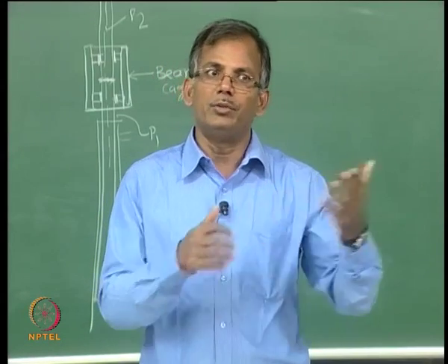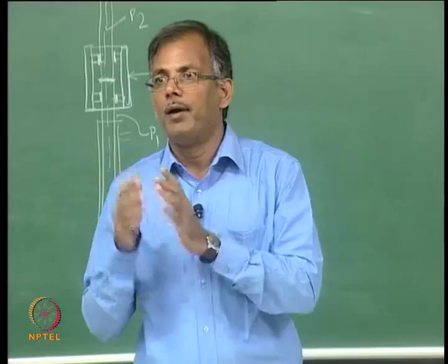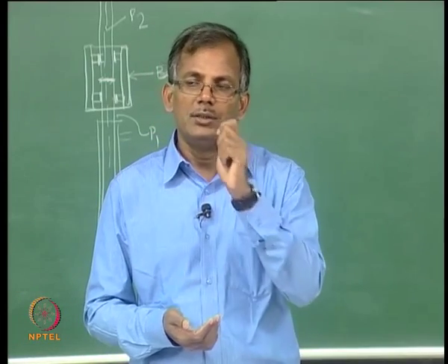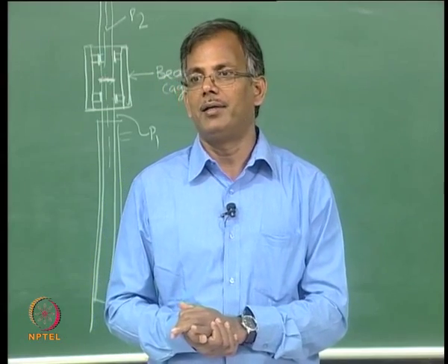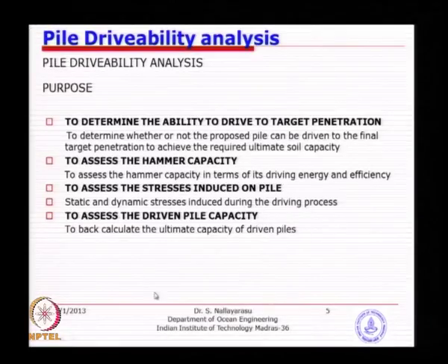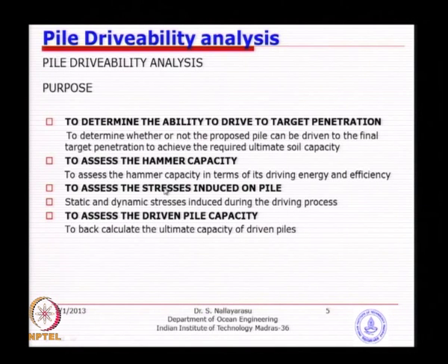Like steel, you might use a mild steel, or you can go for a high strength steel or ultra high strength steel, so that the tensile stress values are higher. So, you do not need to worry about failure. Basically, the assessment of stresses is to make sure that the pile you selected is suitable.